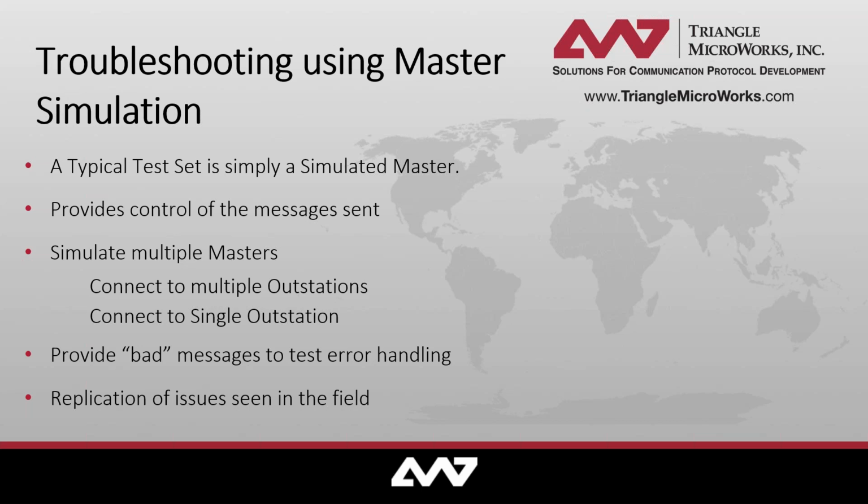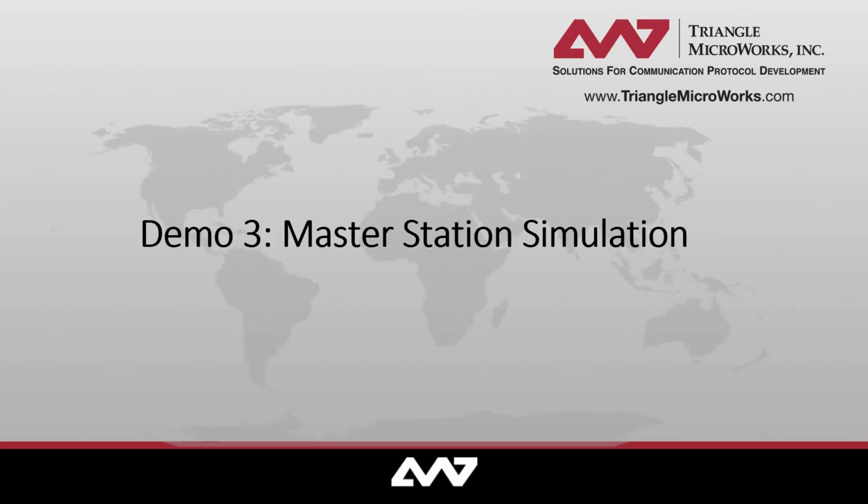Other tests you can perform with a simulator are sending bad messages from the master to the outstation and verifying it performs properly under these abnormal situations. These bad messages may not be easily sent from an actual hardware master device. So let's take a look at how you can simulate a DNP3 master in the test harness.